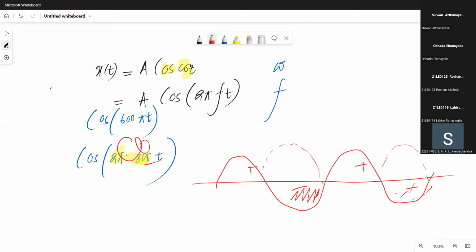So this simply refers to half wave rectification and full wave rectification. In full wave rectification, we can model it as 2 times the previous frequency, so the frequency gets doubled. Once you convert the sine squared or cos squared into a linear term, we have the frequencies at 2 times the original angular frequency. And keep in mind, in addition to that, we are getting a DC signal as well.